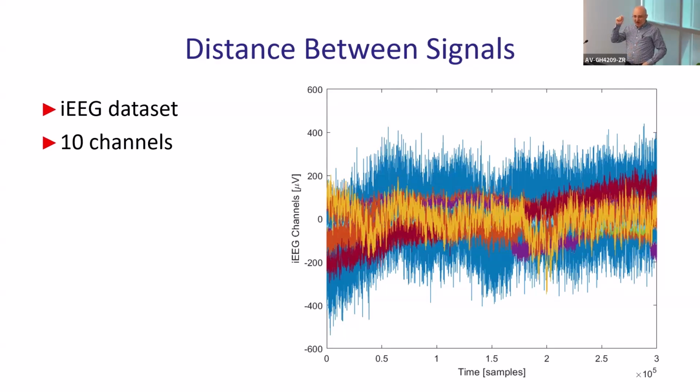Okay, brain signals are microvolts, which are super tiny signals. Recording them is very difficult. You don't have ground, which means all of them are floating on an absolutely virtual ground. So you cannot connect the patient to the main power, okay? Not safe. So they are all insulated from the mains power, obviously. So you have a reference, which they typically measure behind the ear, or somewhere in the middle here, or average between 2 ears, like mastoids, they put it on mastoids.